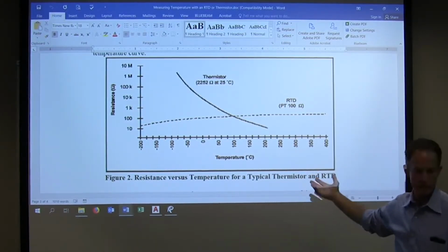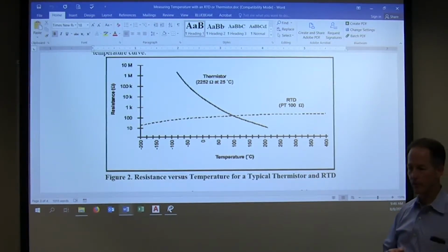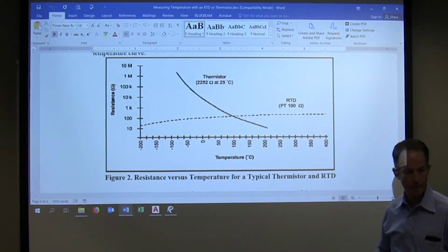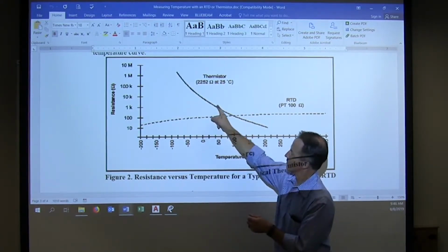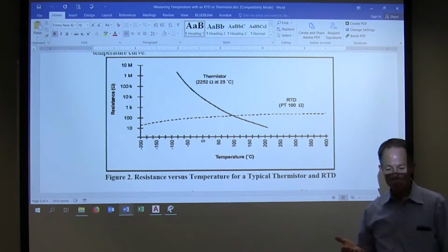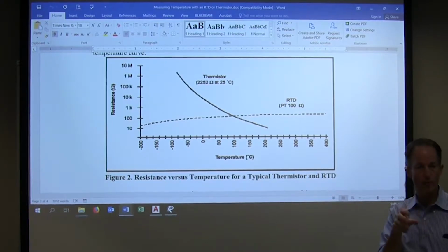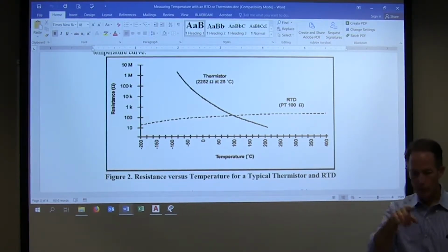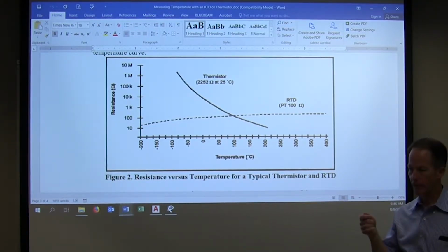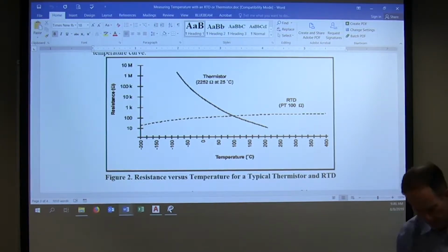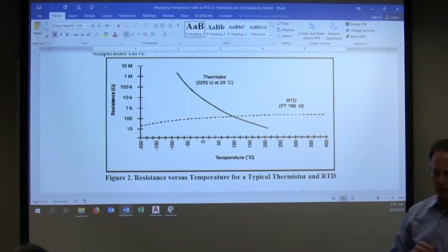You've got to know what you're dealing with. When you go out in the field and have to troubleshoot a sensor, you're going to have this in your pocket, right? Pull it out. You get your magnifying glass out. No, you're not going to do that. But understanding the properties of how these sensors work will help you as you troubleshoot problems. Now, the sensors we have here that we're going to play with in a little bit are 20,000 ohm at 77 degrees. So on the chart that you have here, it is the far right column. Those are the pre-con type 4s.